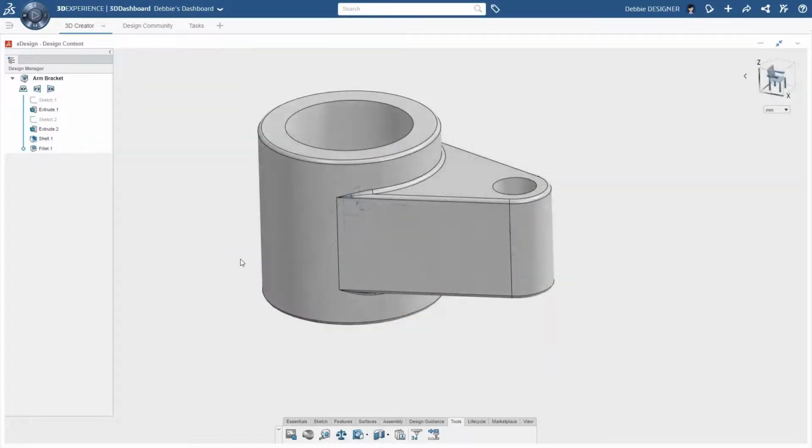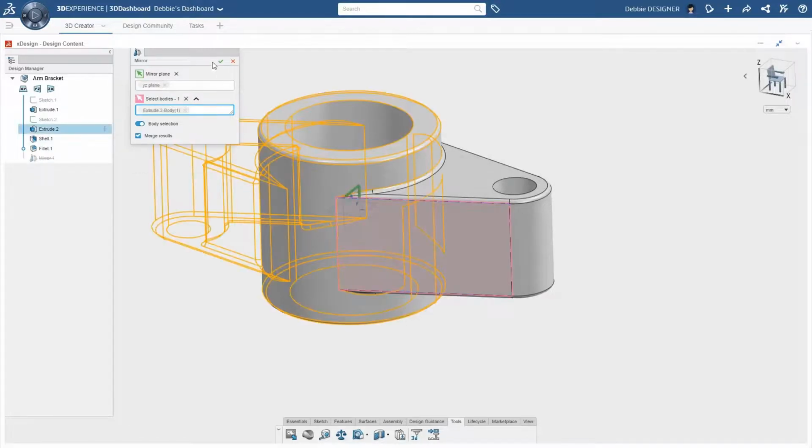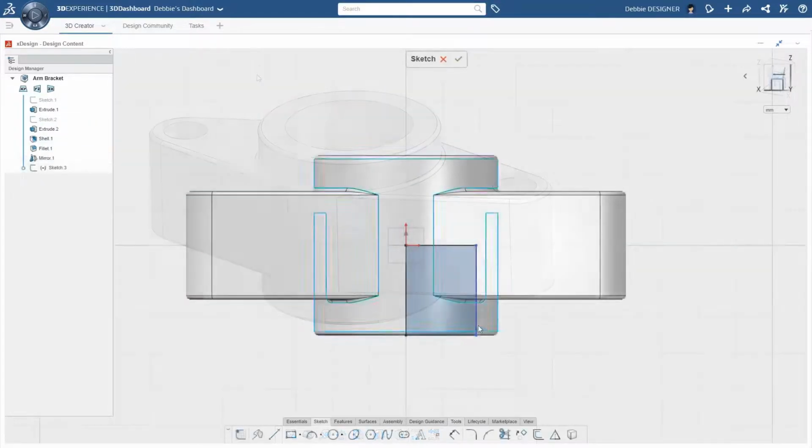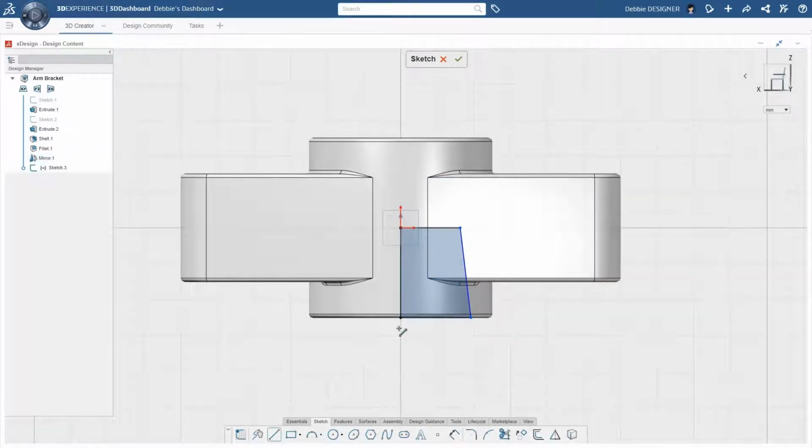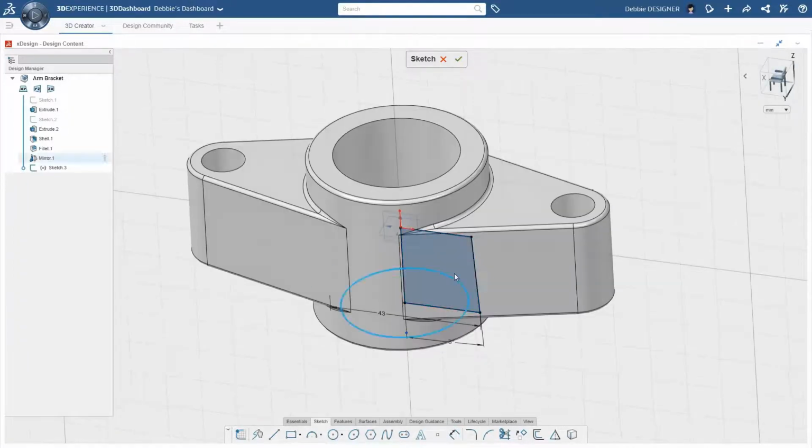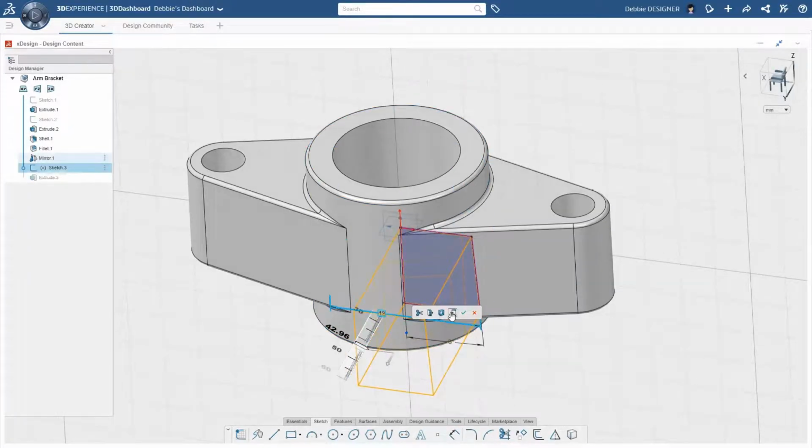The bottom features require a taper, so she will use a revolve cut, but she uses a shortcut to drag the sketch profile out. This is important because in other CAD solutions you would be required to exit the command and start over again. This isn't the case in XDesign.